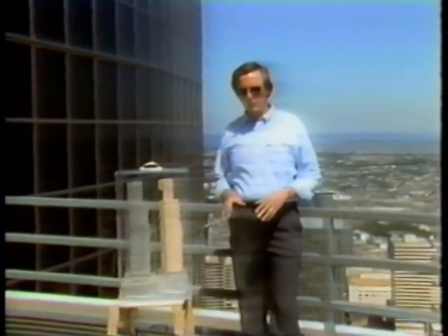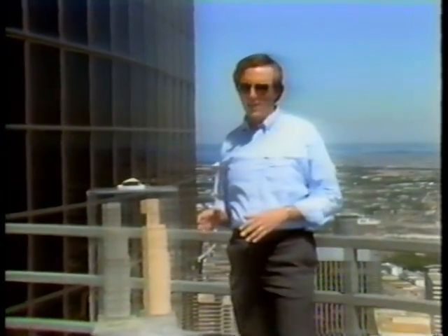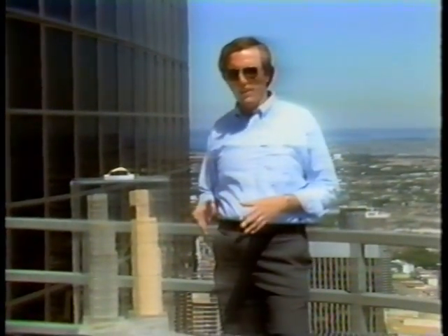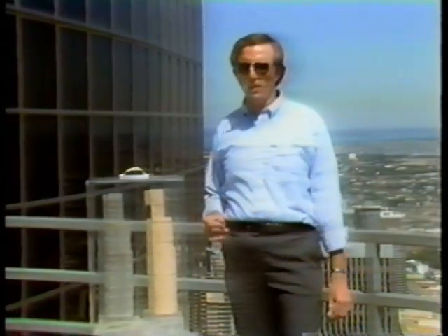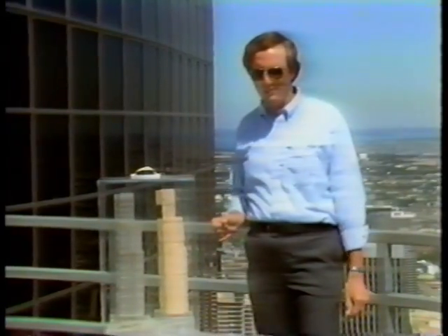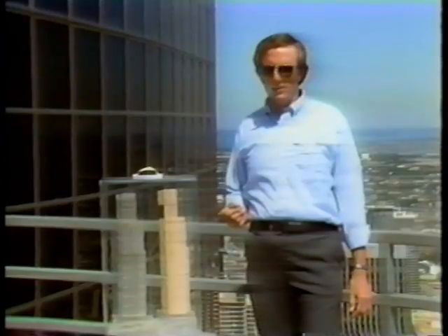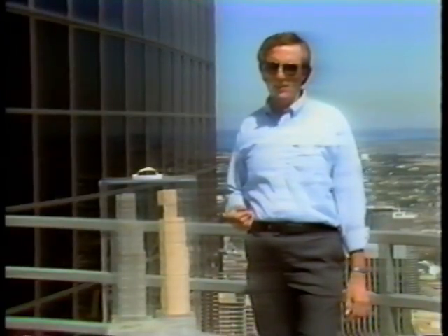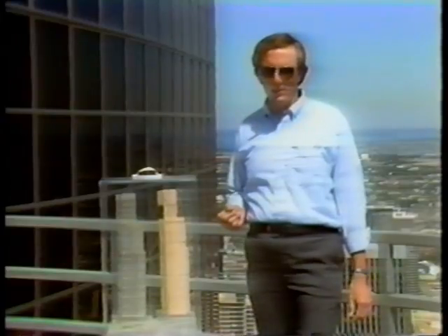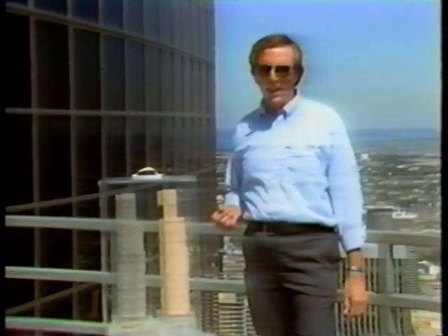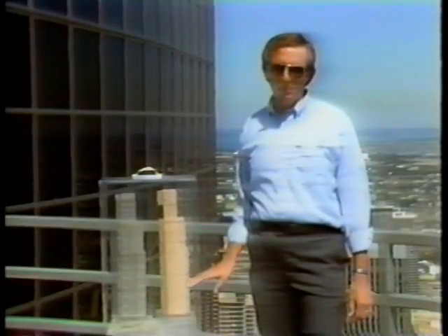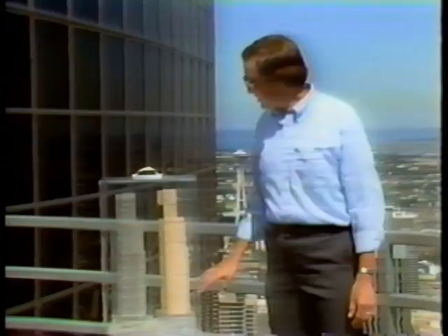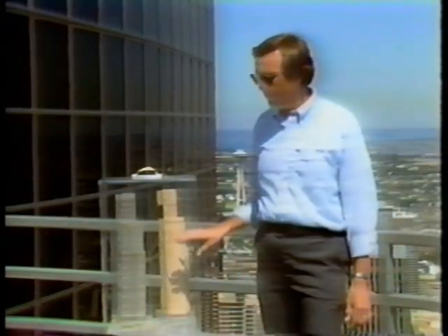Tall building like Columbia Center sways in the wind at its fundamental period of vibration. Columbia Center is very stiff building for its height, and those periods of vibration are in the range of 4 to 5 seconds. The period of vibration determines, to some degree, the accelerations and forces that the building experiences, and we need to know these for design of the building, and also to determine if the occupants are going to be comfortable under those acceleration levels. To do this, it's much too complicated to apply conventional theory, so wind tunnel testing is employed.